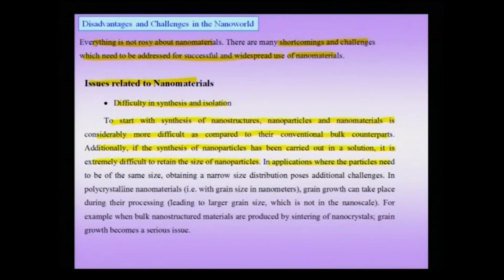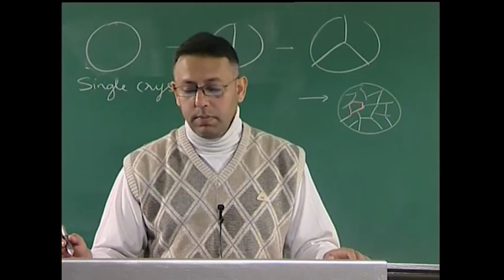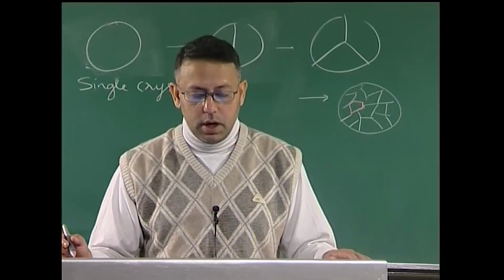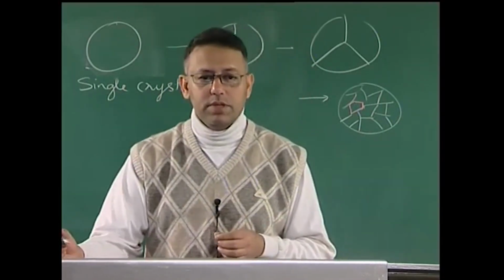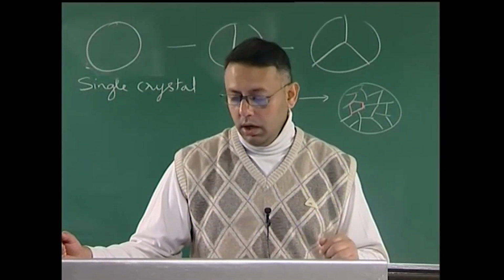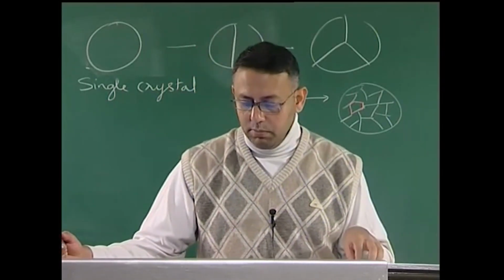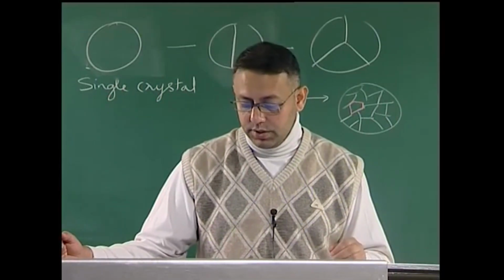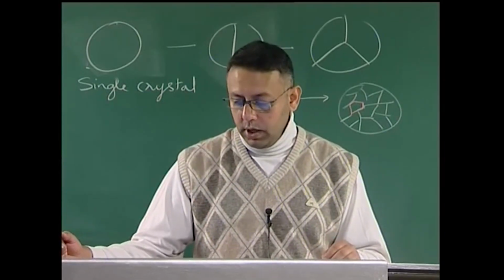In applications where the particles need to be of the same size, obtaining a narrow size distribution poses additional challenges. More often than not, we do not want particles of various sizes to coexist, because if I am depending on, for instance, absorption of a specific wavelength, or a certain other property which is now going to be dependent on the grain size, if I have too wide a grain size variation or too many particle sizes involved, then I will obviously not get the specific property enhancement which I am looking for. Therefore, I want to get a narrow size distribution, and this is definitely a challenge when it comes to nanomaterials.